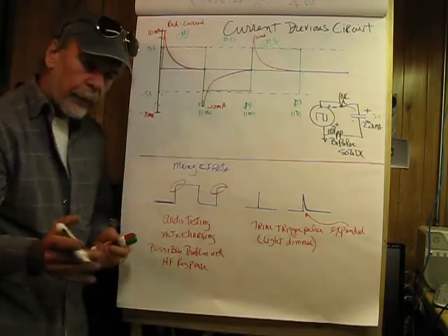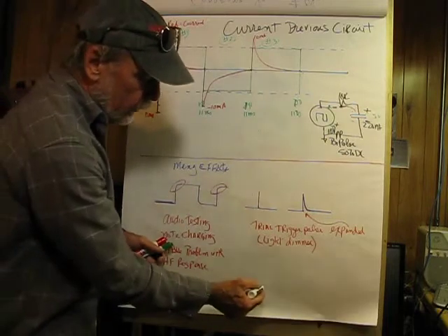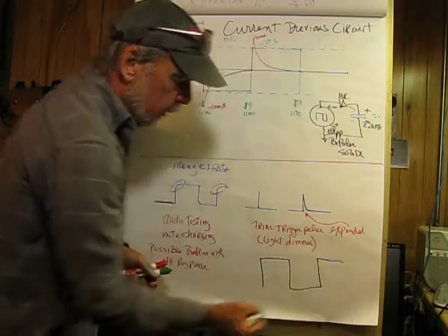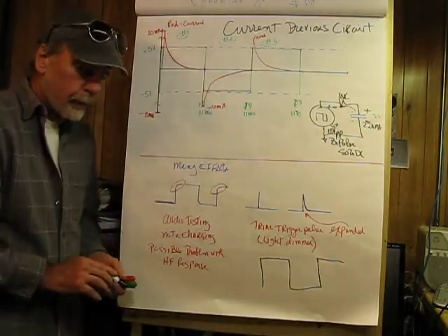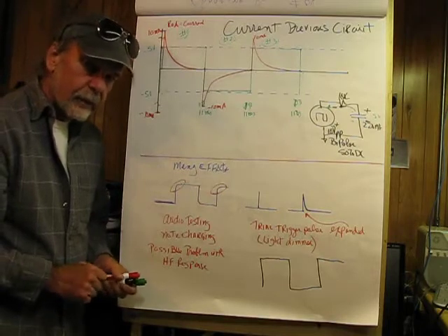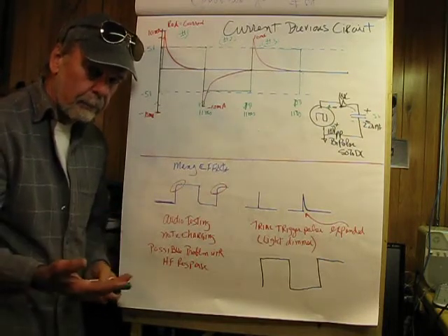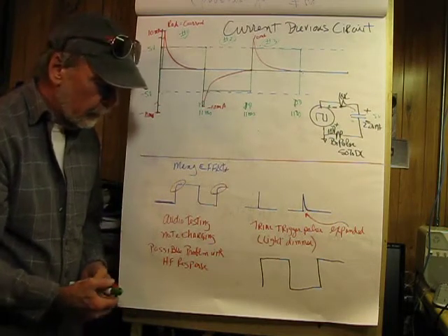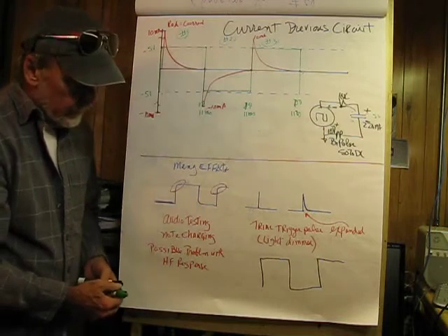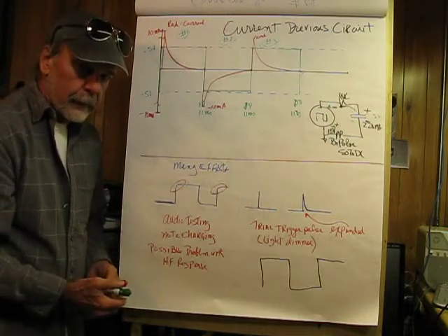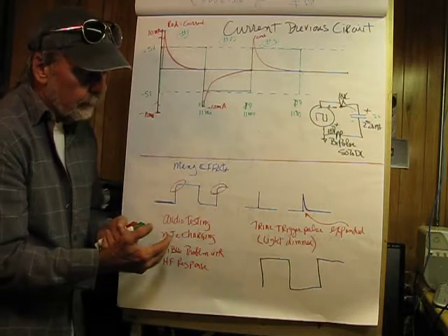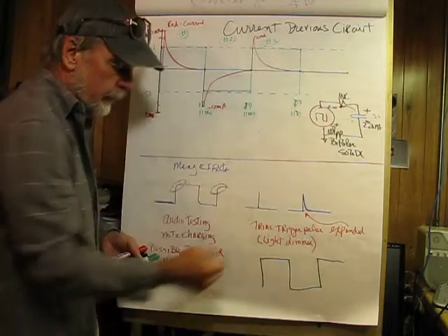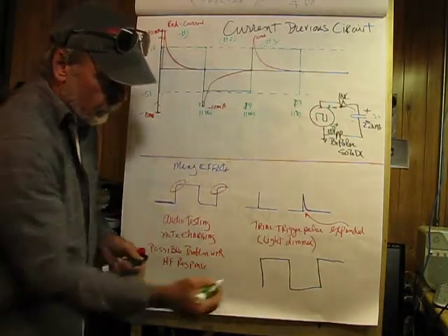Let me put down one other, since I'm thinking about it. If we have a low frequency square wave, say 50 Hertz, and we're viewing this on a scope, and the scope is set to DC, and what DC means is direct couple. 3 different definitions of DC: direct current, direct couple, and duty cycle. And if we were to flip that to AC coupling, what that means is that the scope is going to put a capacitor in series with its internal impedance. So it's going to flip these 2 parts around, and then what we would be seeing here is something which would look like this.